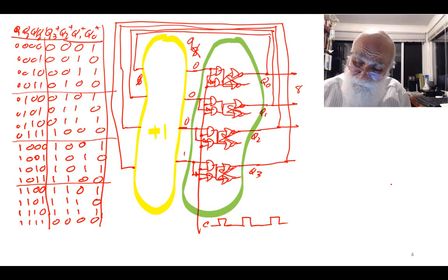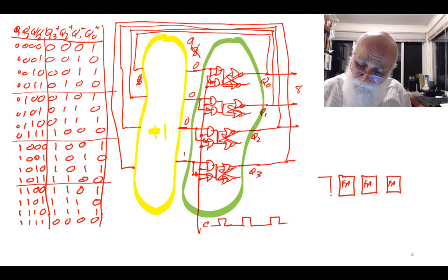That's an incrementer. An incrementer is a full adder for now. Remember we said from last time that the carry out goes here, carry out goes here, carry out goes here. Okay, and then we have a carry in.